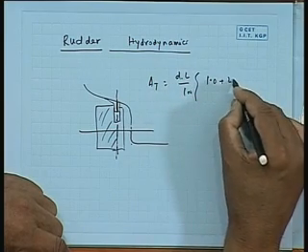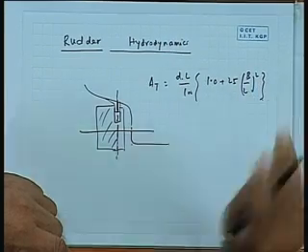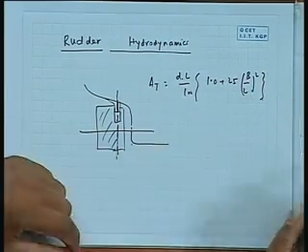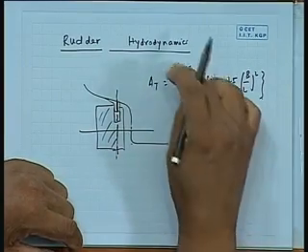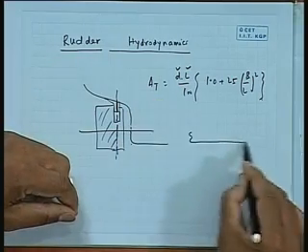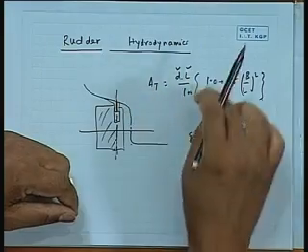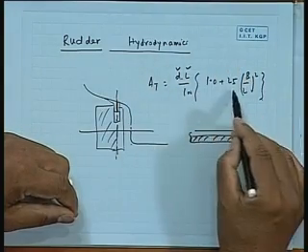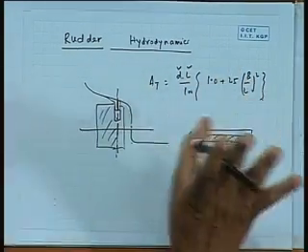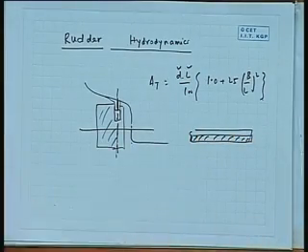I will just give you one formula here, etc., and these are the various kinds of formulas. Obviously dL by 100 gives you the percentage. The dL is, for a ship, the center plane area, more or less this area. So AT is some kind of percentage of that. As I say, if you work it out, this will turn out to be again around 1 or 2% or so. The purpose of today's talk is how rudder produces force, how the cross section looks like, and some detail regarding its performance.